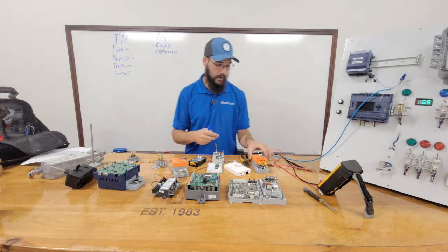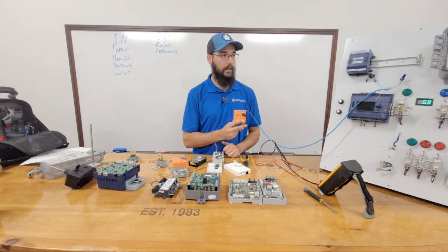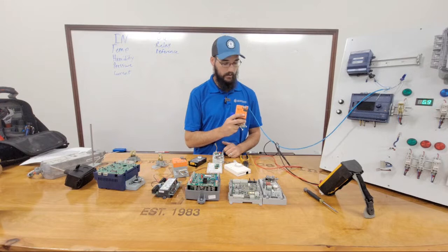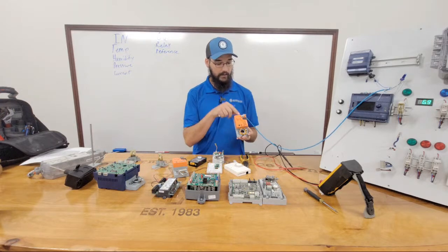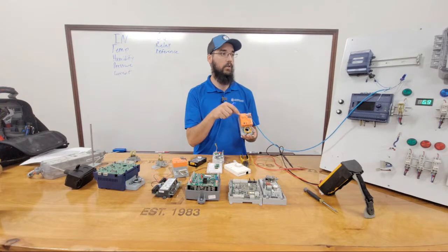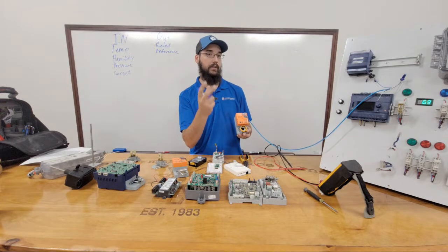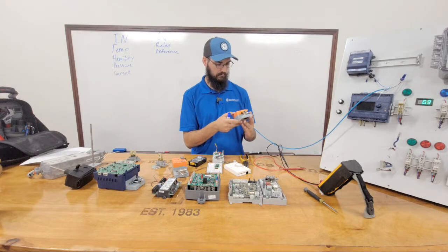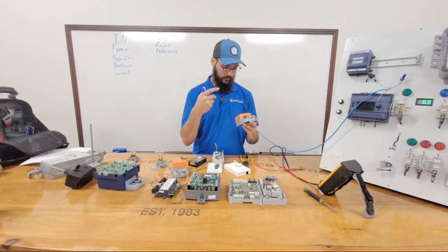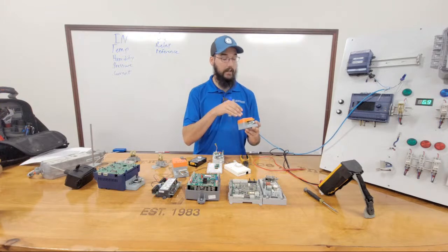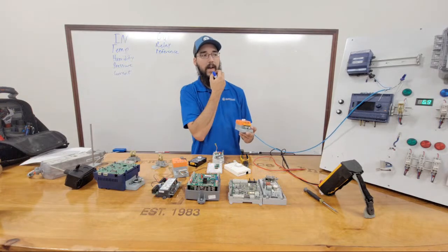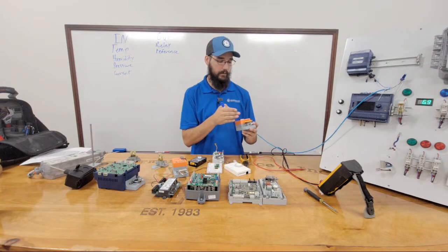And at the same time, this is an actuator, meaning that I need to send this thing 24 volts on one set of terminals, and I need to give it a 0 to 10 volt, right? This one's, no, this one's 2 to 10. I need to give it 2 to 10 volts DC in order for it to pick the position.